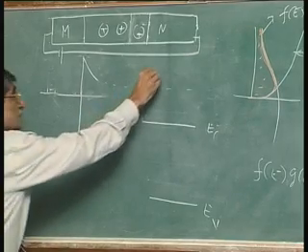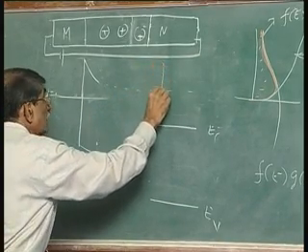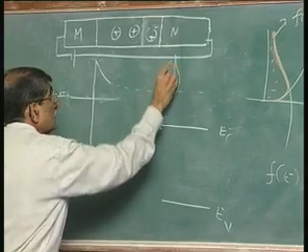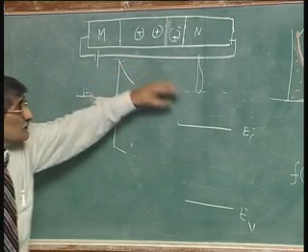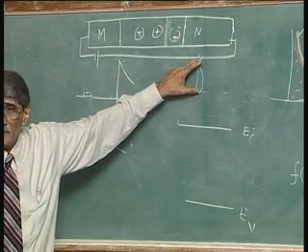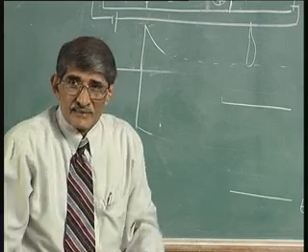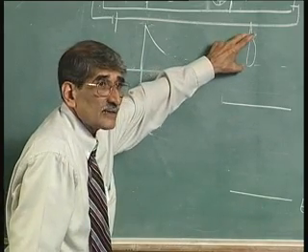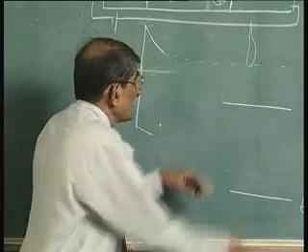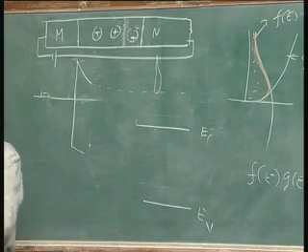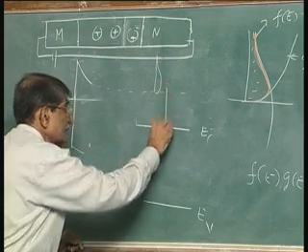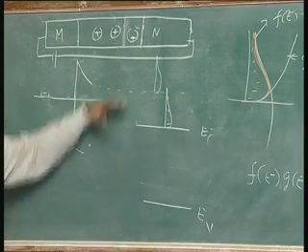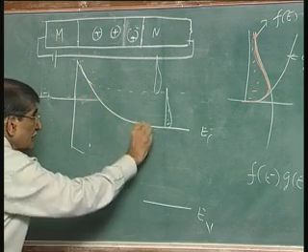Now, what about this portion? What was originally here, which was going above like that, some of them were able to cross. Okay. This level is the kinetic energy of the electrons. The kinetic energy is 0, the entire energy is potential energy here. So as you go up, that is thermal energy, because of kinetic energy. When you push the conduction band down, you are bringing the potential energy down. The kinetic energy remains the same, guided by temperature. So this distribution in the neutral region remains the same. The whole level has come down, and from here it is coming down like that.